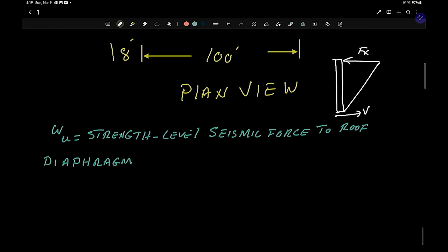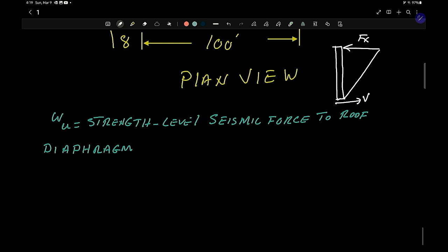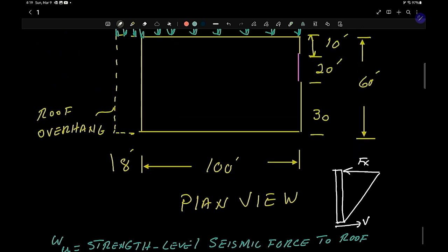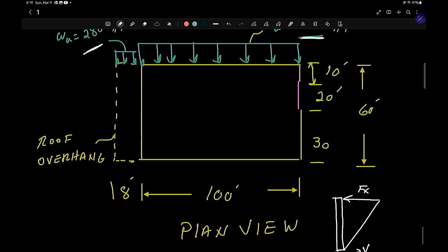So anyway, let's come back in here. One of the first things we want to calculate is the reaction force from this load right here. Let's find the reaction force R1 here and reaction force R2 right here. This wall right here, let's call this shear wall 1, and this wall here, coming down like this, will be shear wall number 2. So that's the reaction R.